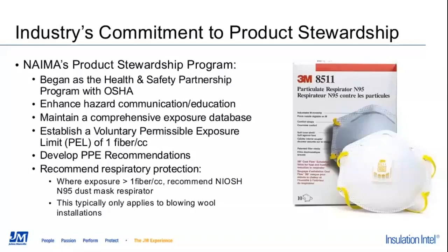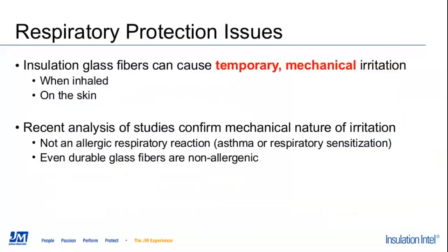And again, the recommended respiratory protection was that N95 NIOSH dust mask that you see right there on the right side of your screen. And this is, like I said, you're only really going to encounter fiber concentrations that heavy when you're doing a blowing wool installation. Once these fibers have settled, it's not going to be in the air as a constant thing. And if you see those N95 dust masks on the store shelves, you want to grab them because they are in short supply right now.